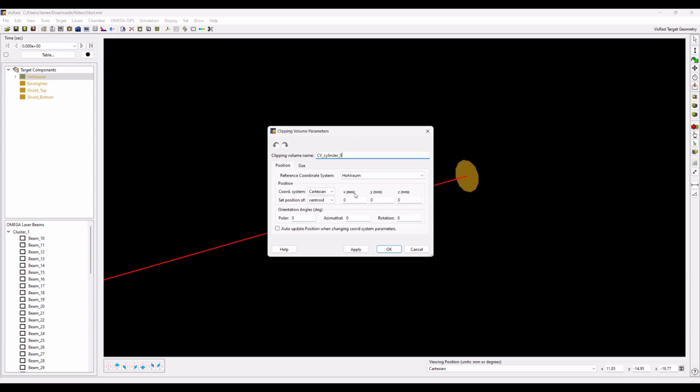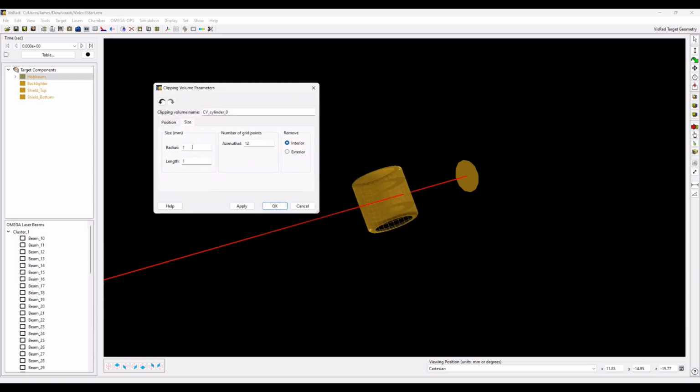We just found this position of our clipping volume. So we know it's in cylindrical coordinates in the reference coordinate system of our hole realm. So I can go ahead and paste in that intersection point, the first from our intersection point list. And for the orientation, we just use our azimuthal angle of 288 from right here. And we want to flip it 90 degrees so that this cutout is facing outwards, perpendicular to the surface of our hole realm. For the size of our cutout, we're just going to use a radius of 0.15 and a length of 0.3. The length is a little arbitrary.